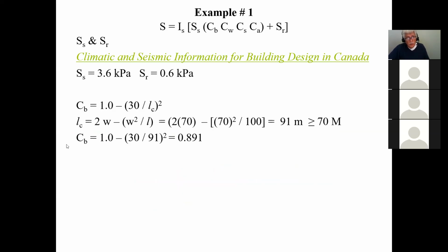Now, once you calculate your CB value, of course, CW: when it comes to schools, any high or post-disaster building, you can't use anything less than 1.0. That's required by code. So right away, my wind exposure factor, CW, is 1.0. Now, I've got a flat roof. Therefore, I know that under 30 degrees I have to use 1.0. I can't take advantage of a slope. I have no obstructions on the roof, and so on, and therefore my shape factor ends up being 1.0.